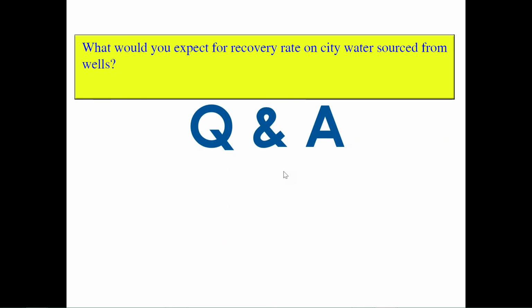You can supersaturate calcium sulfate, for example, and therefore get to higher recovery rates in a Desalitech system than you would be able to with conventional RO. But how high a recovery rate you can go really depends on the specific water chemistry. We've seen recovery rates as high as 98% on pretty good quality water coming into a Desalitech system. Other times we're limited at lower recovery rates by scaling. You can adjust pH and use antiscalants in the same fashion that you would use them in a conventional RO system.